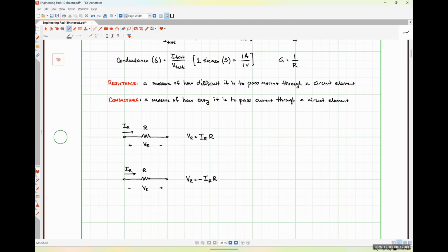Let's talk about the reason why we have to do this. So a resistor, what does it do fundamentally? Let's start there. Okay. What was that? Turns current into heat. Okay. So it converts electrical energy into thermal energy, but that's just a little bit more formal way of saying exactly what Matthew just said. Okay. All a resistor can ever do is convert electrical energy into heat.